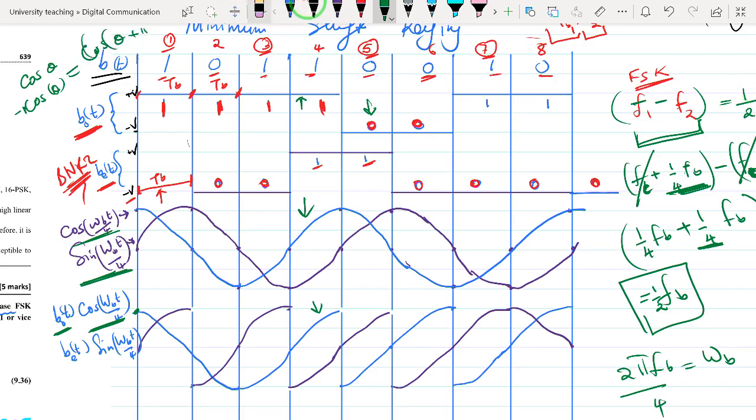So that is what we are doing here. When we multiply our cosine with -1, arising from this odd data stream, it is going to shift phase. You can see this shift in phase: it was going up, it was at the center at the top of the wave, and it changes the phase by 180 degrees. It is now going up instead of going down.